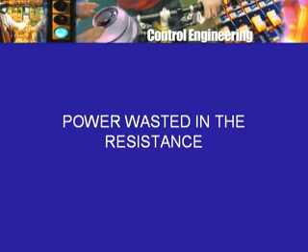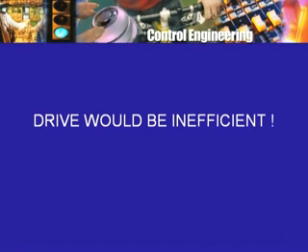In other words, your drive is running at the correct speed perhaps, but it is inefficient. It is considerably inefficient. The motor is drawing the same power, although the power that is being supplied to the load is 1/3. And one can see why it is 1/3. The torque is the same, we have assumed that the torque is the same, but the speed is 1/3. So the mechanical power required by the load is 1/3. So the efficiency of the drive, if originally it was close to 100%, it can't be 100%, will now be of the order of 30% or so. So obviously this solution is not the correct one.